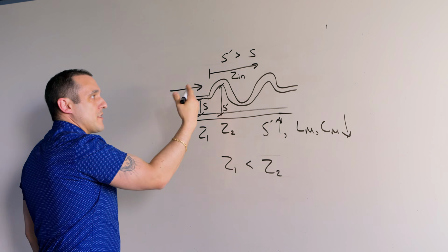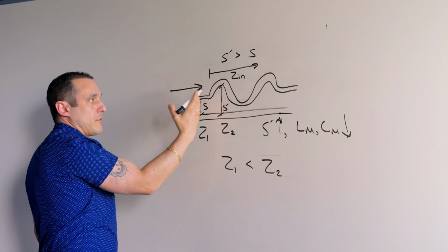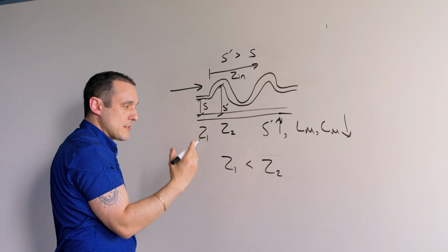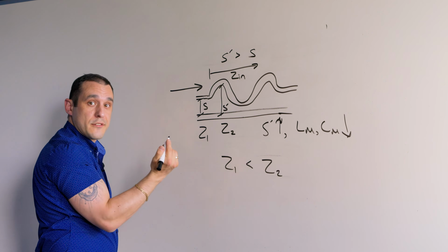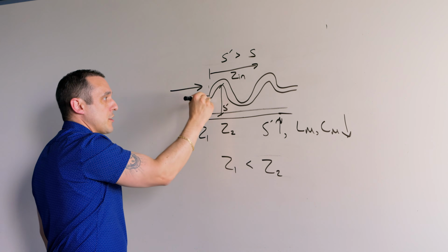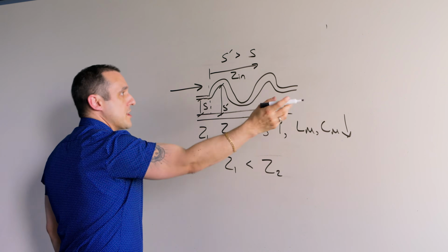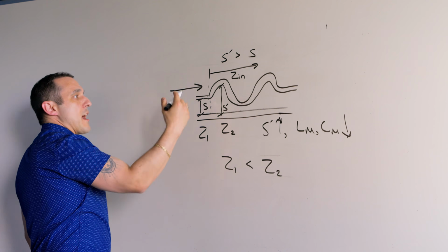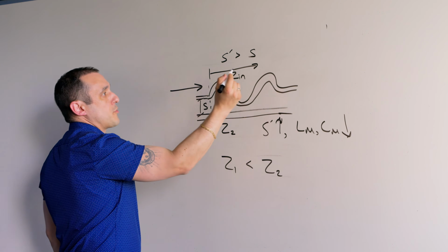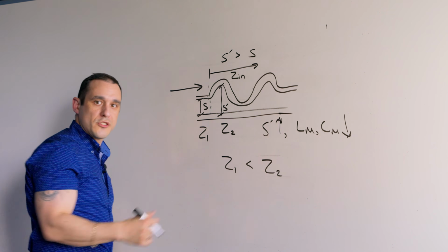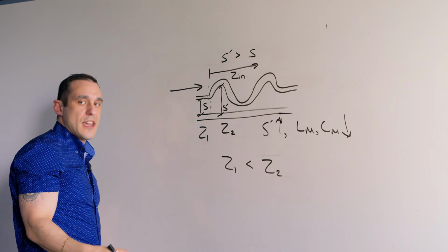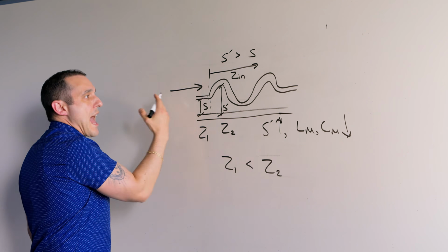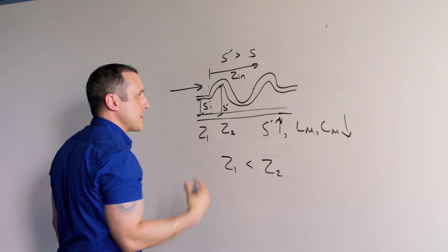And of course, if a signal travels along and encounters this input impedance, there can be a reflection right here. So there's some slight reflection that happens at this interface looking through this length tuning section. And that reflection can continue right here at this point and right here at this point and so on and so forth, wherever we have these impedance deviations. So you get these reflections as the signal starts to travel through this length tuning section.